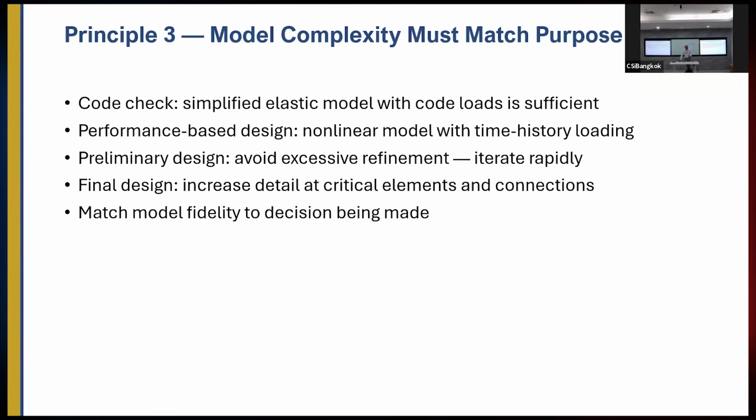What is the purpose of this particular analysis? Is it a preliminary design for checking sizes, or is it the final design to submit to the authorities? Why am I doing this? Am I checking the stresses? Am I checking the bending moment? Am I checking the deflections? If you're just checking the deflections of the overall drift, you don't need a lot of things on the floor. It doesn't matter. If you're designing the floor, then you need the details of the floor and openings and stuff like that. But if you're checking the natural period of the building, the floor is not even important there. It doesn't matter. It won't alter any of the modes because they're global. So the purpose of the model and the model should match with each other.